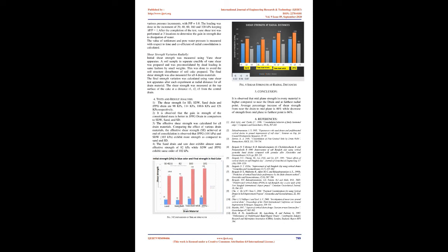These increments are given by means of dead load with porous stone on the top of the clay sample topped by filter paper, so that during consolidation water gets removed through the porous stone. These increments of static loads are to be kept for a longer period of time, at least 48 hours. Increments are calculated as shown below. A representative sample for determination of water content was taken and measured.